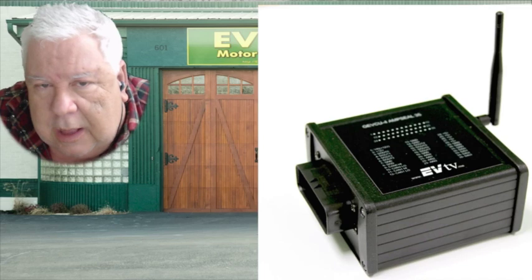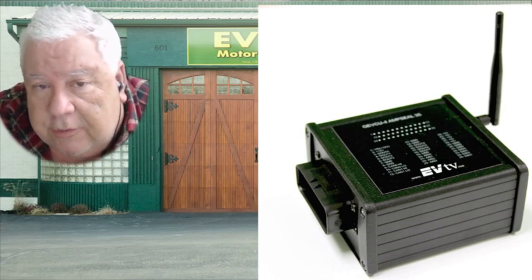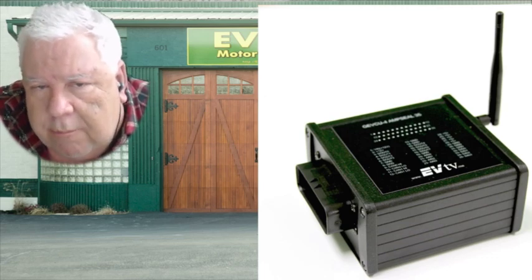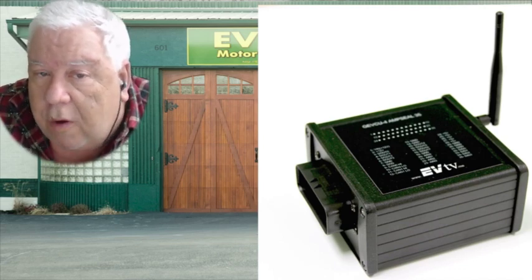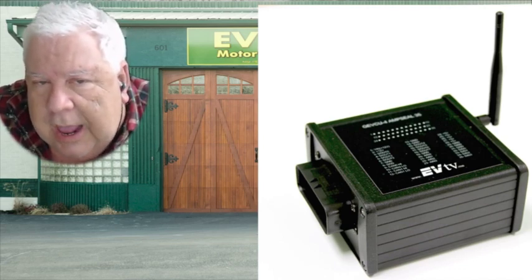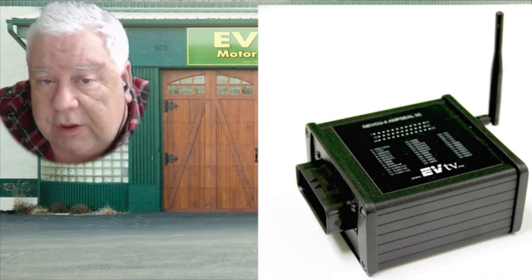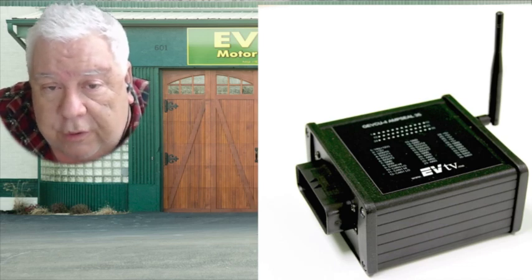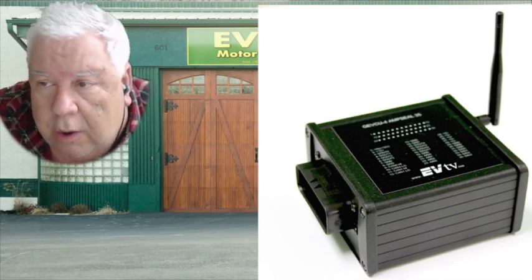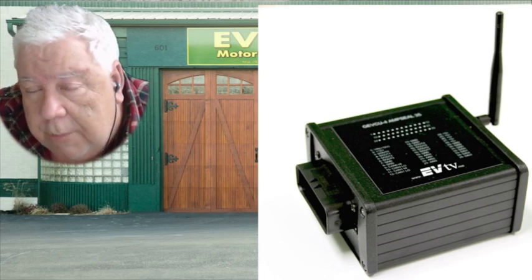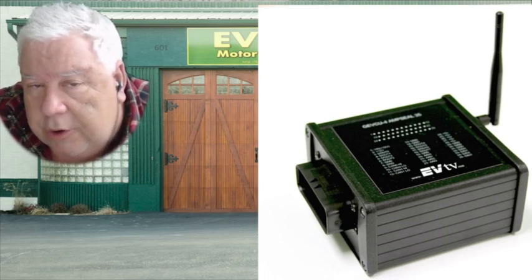The key element of the VCU is that it's in software and it's considered proprietary by the manufacturer. If they need to change or upgrade it for that particular vehicle, they issue a recall and have all the people that have the vehicle bring it into the dealer and flash new software in it to make the changes. There are no configurable items in it that even can be made at the dealership, much less by the end user. If you want more regenerative braking or less regenerative braking, don't want it on the throttle or do want it on the throttle, you kind of have to buy a car that's set up that way. You don't get to change any of that.